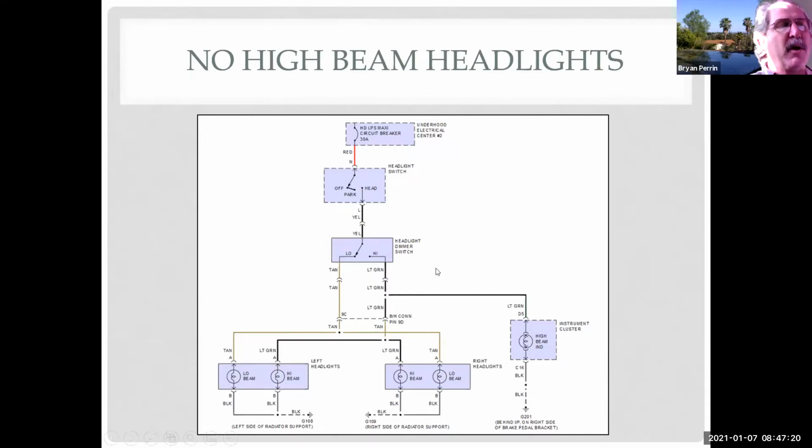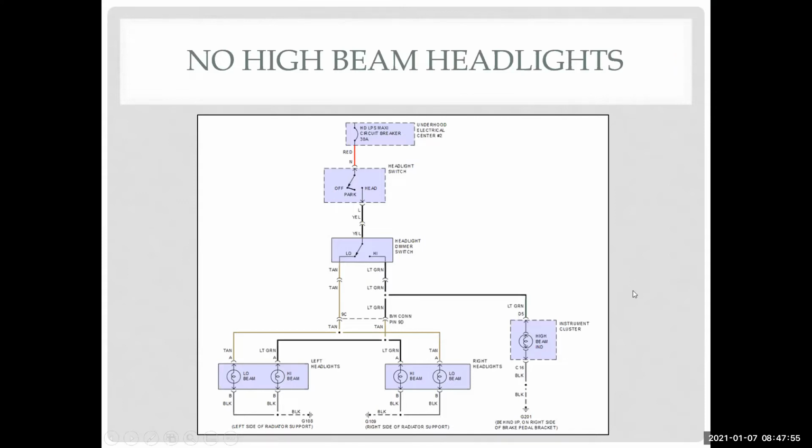Also, these aftermarket schematics are made with what's called pre-production diagrams. In other words, we expect to make the car this way. So we expect to use a green wire with a red stripe. But you know what? They were out of that. And so instead we used an orange wire with a yellow stripe. So if I'm using an aftermarket schematic and I'm looking for that green wire, I'm never going to find it because it was never built that way. The factory diagrams are updated after they build the cars. So a lot of times you'll see a wiring color difference with aftermarket schematics. Not all the time, but it's definitely not uncommon, and that's why that happens.